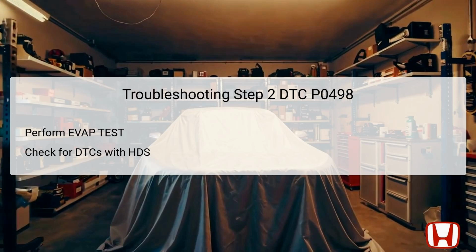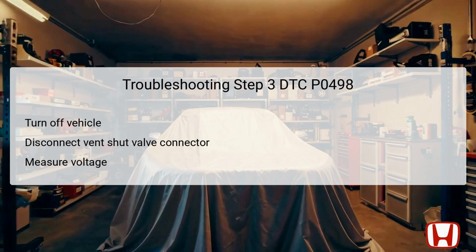For Step 3 in troubleshooting DTC P0498, begin by turning the vehicle's ignition to the off lock mode. This ensures that all electrical systems are properly deactivated before connecting or disconnecting components. Next, disconnect the 2P connector linked to the EVAP canister vent shut valve, isolating it from the electrical supply.